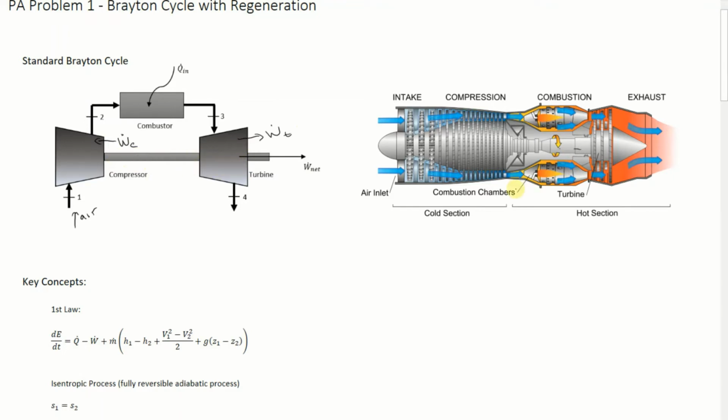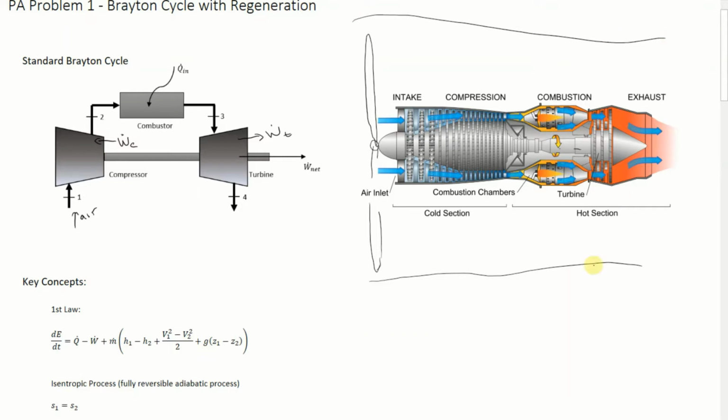So to relate this to the real world, this is a gas turbine engine. One application that many of you would have seen is that an aircraft engine uses this type of engine. With most aircraft engines, you'd be flying with a turbofan engine, which is that large fan with the spiral design on the end that you see at the front of an airplane. With these, a lot of the thrust actually comes from the spinning of that fan, not from the air passing through the turbine, and so there's this large bypass section. But the insides of the turbine are what we modeled with the Brayton cycle.